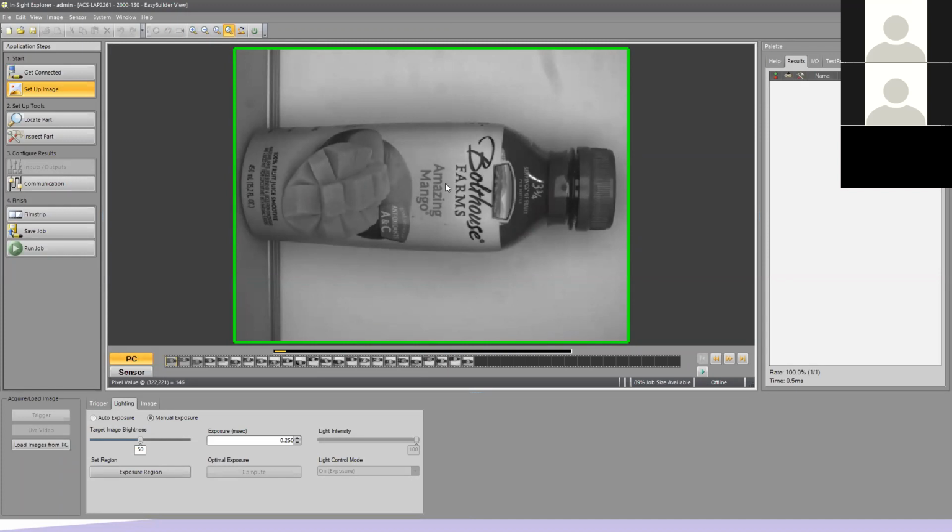By having the longest axis of my imaging chip in orientation with the height of my part, I'm able to fill up the field of view more to see more smaller details of the part. Had I set it up where the part was going against the narrow part of my imaging chip, I would have had to have been farther away, and I wouldn't have been able to see as many details.